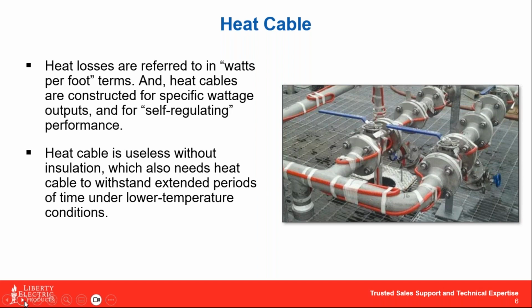To reiterate what we just mentioned on that previous slide, heat trace cable is basically useless without insulation to cover it and hold that heat into the skin of the pipe. Looking at this picture to the right, if these heat cables were working on a 30-degree day, they're emitting literally 95% of their heat to the ambient air. So it's not doing you much good for whatever's inside the pipe. Insulation goes hand in hand with your heat trace cable.